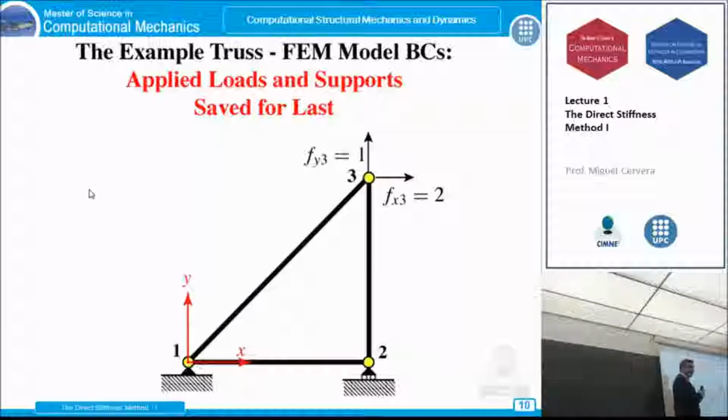On the other hand, in those degrees of freedom where I'm specifying the displacement, I cannot specify the force, because the force will be given a posteriori, it will be a reaction. So at this stage, I can say, the problem I have to solve is, first, find out the displacement which is free here and the 2 displacements which are free here.